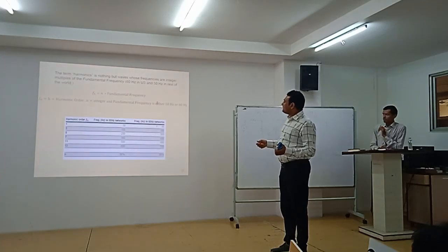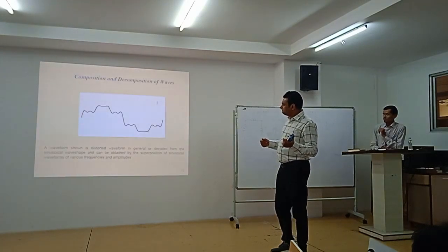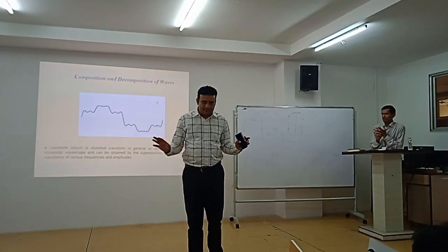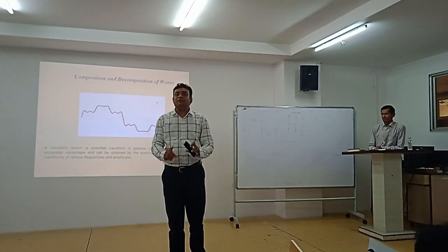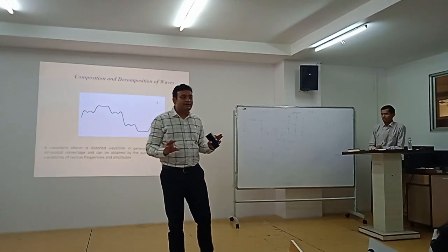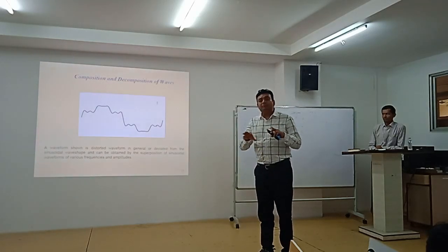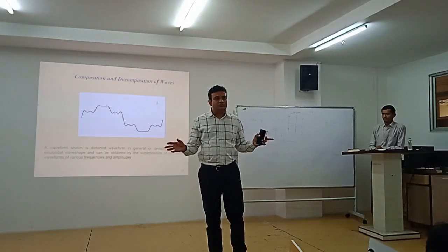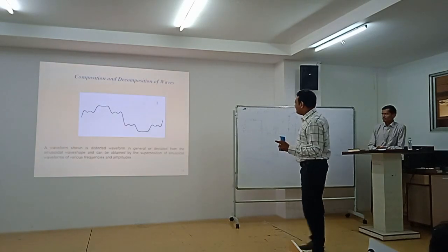Again, there are two ways of defining harmonics. Look, I have got one wave which is completely distorted. It is no more a sinusoid. So how do we get its frequency information, that there is a fifth harmonic, seventh harmonic, eighth harmonic, 10th harmonic? FFT. Right? FFT decomposes it into the various frequency spectra, so that you can come to know that this harmonic content is there in the waveform. Right? Next.